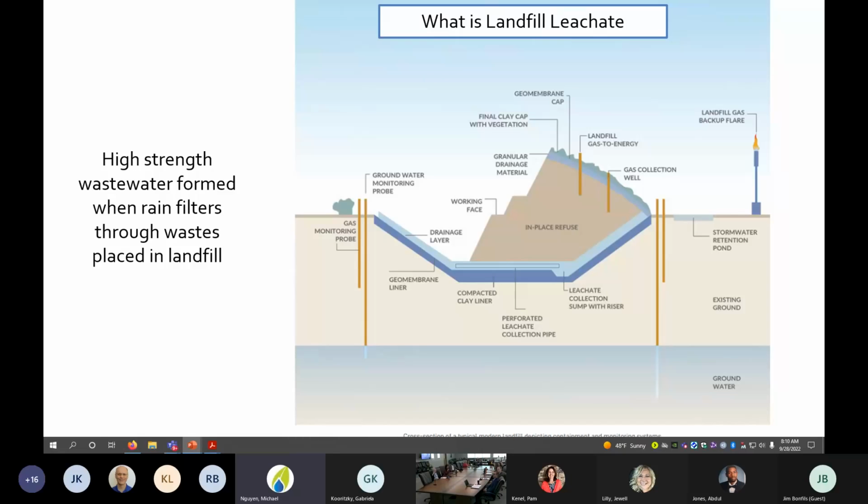So even on dry days, we're getting leachate, right? There's always water in there, but when it rains, that can increase by a factor of 100, right? What we get out of that is really open stormwater coming right through there and being pumped to the wastewater treatment system. And it's this contact with the material that is taking the rainwater, accumulating all of that PFAS and many other contaminants, and we're getting a high strength waste out the bottom.